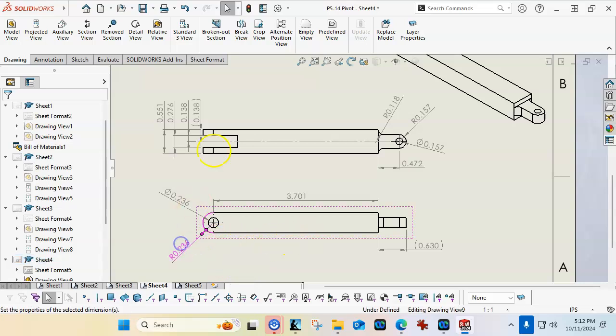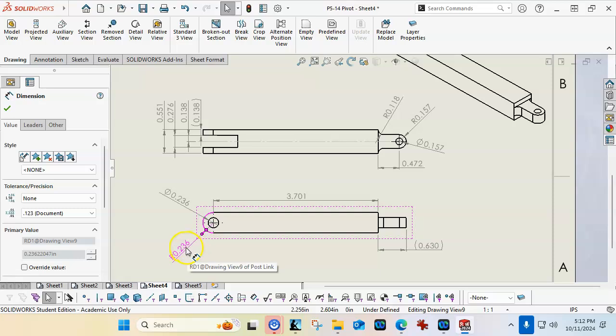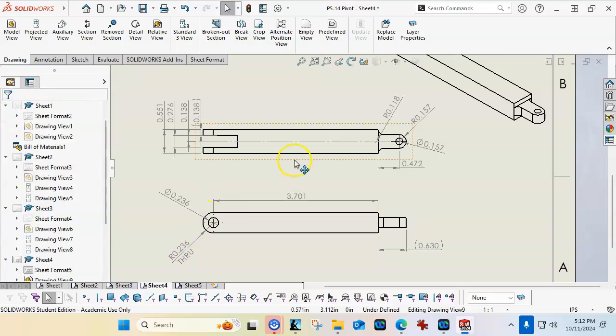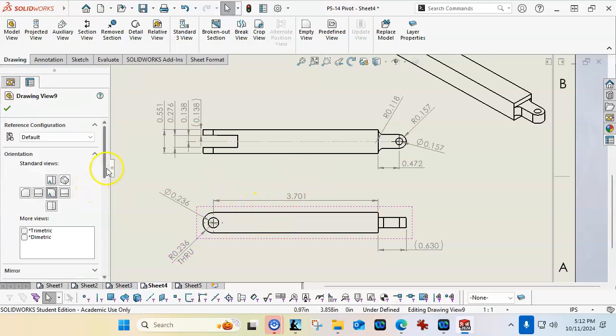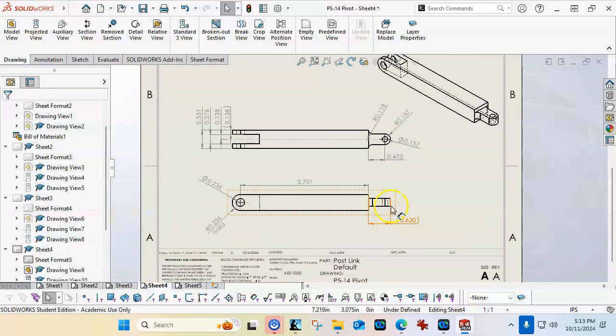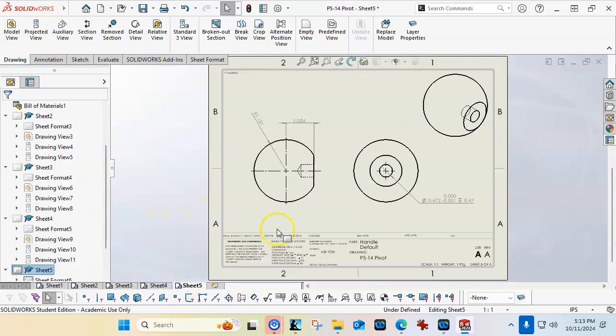All right, so that one we would kind of assume through all, but just to be on the safe side, we could add a through. And if we did add in the hidden line shown, does it add enough detail there to show that it's through? I mean, those are kind of the questions. Err on the side of it makes more sense, or we'll fill in the blanks.